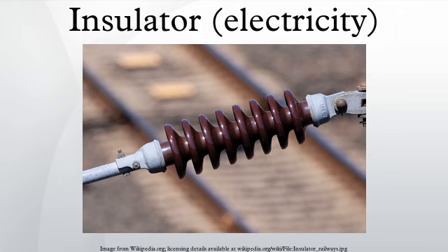Guy wires supporting antenna masts usually have strain insulators inserted in the cable run, to keep the high voltages on the antenna from short-circuiting to ground or creating a shock hazard. Often guy cables have several insulators, placed to break up the cable into lengths that are not submultiples of the transmitting wavelength to avoid unwanted electrical resonances in the guy.